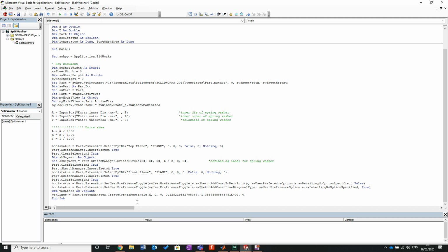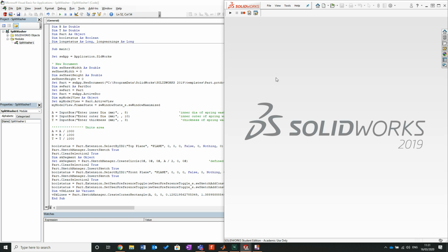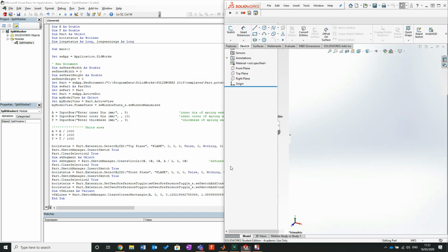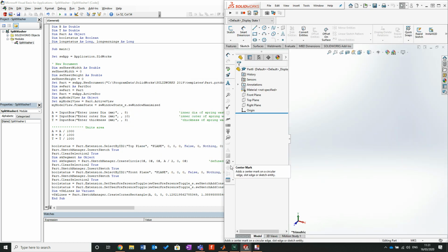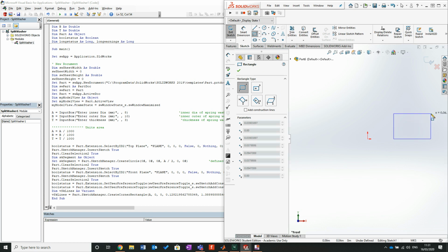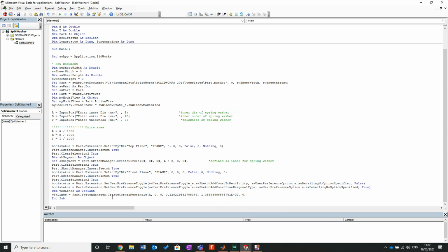So this is purely because I want the corner rectangle to, let me just come back to here. I want the corner rectangle to actually start from the origin of the circle. So that's purely why I'm doing that. It will not have reference to where, in essence, I begin. So in essence, what I'm trying to do is get the corner rectangle to start with a distance across. That distance, in this case, I want it to be connected to the circle. If it's connected to the circle, that means when we go to extrude and we go to revolve, we should be able to have a good idea what's going on. Well, not revolve, more sweep.